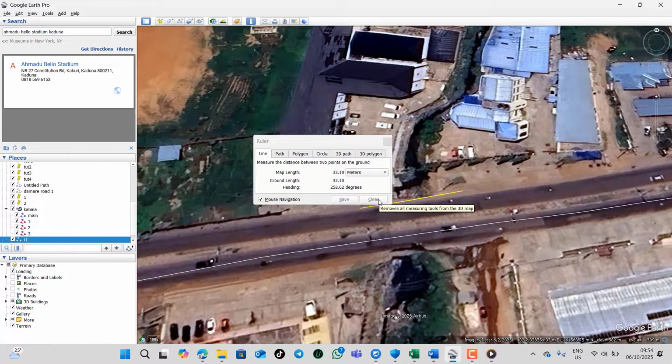We have the highway manual, right? Based on the standard for the highway manual 2013, it is 30 meters for right of way. I think that has been reviewed now, if I'm not mistaken, to around 47.5, I believe, for your right of way. So you check for obstructions along your right of way.